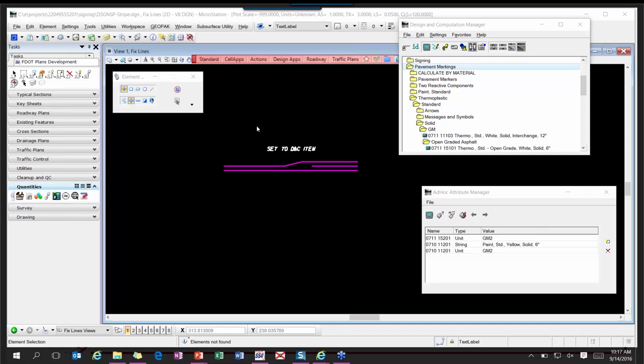And the problem with that is that if it's a high traffic area and you have a lot of turn movement on it, a lot of times it is just not durable enough and it starts to come up and not work like it's supposed to. So preformed is tougher. It's placed all at one time. We recommend preformed on concrete surfaces as well as some of the special marking. We've got some new roundabout approach arrows, and they're the fish hooks. Those will be preformed. Any of your bike lane markings, those are preformed.